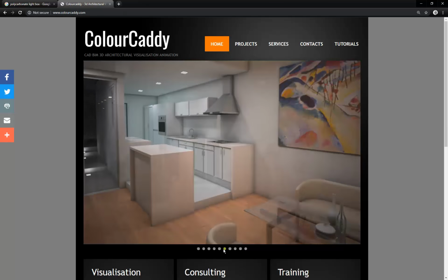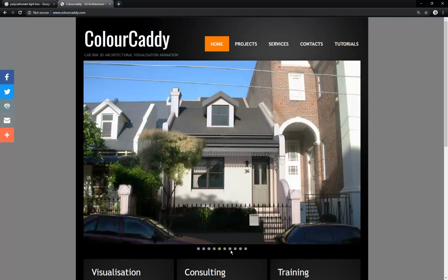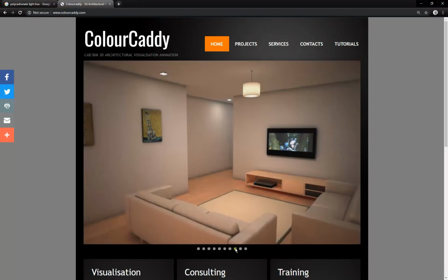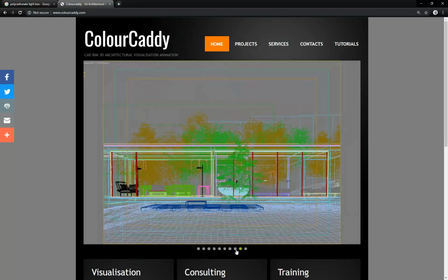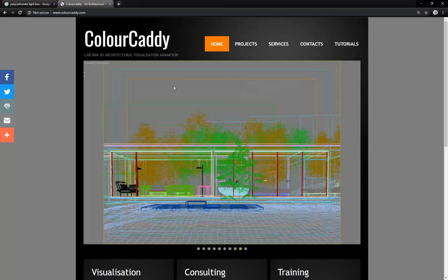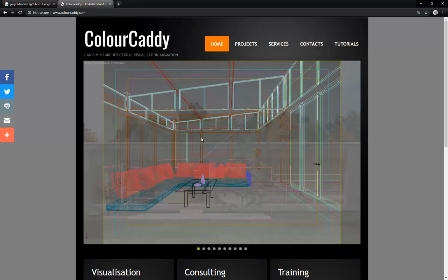So especially when you've got lights close to surfaces like walls. Well, going back to here. So, they're not too bad, but these in the lounge room, because the lights are going up to the wall, it took me a few hours to get that light level just right to not overblow. Well, I mean, it worked for all the lights. And then, yeah, so that's sunlight again.